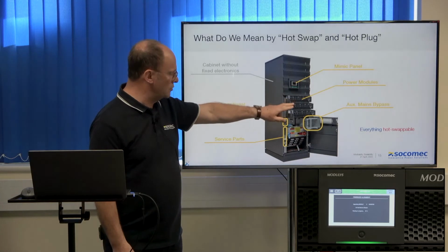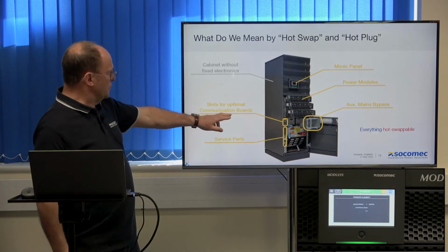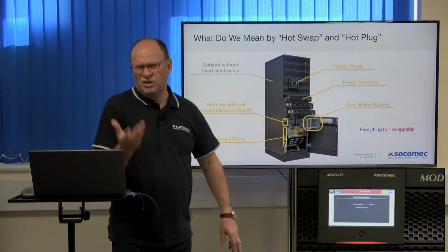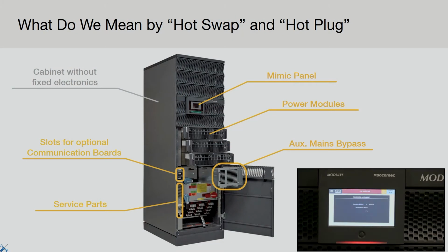Power modules we've talked about, static bypass we've talked about. There's some slots for the communications, so your Ethernet connections, your relay alarms, things like that, they can be swapped out. And also there's some service parts, there's some power supplies.